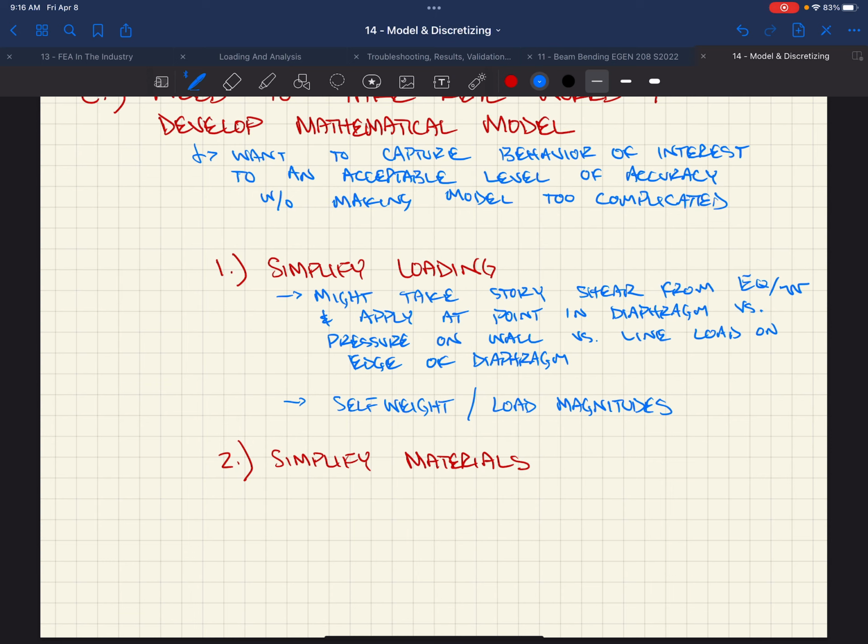And then you would go to that manufacturer and they would say, okay, here's a table: if you have a double wythe wall on the outside, you're gonna need to use this clip at this spacing, right? Maybe 48 inches on center horizontally, 48 inches vertically. And then they do a bunch of testing, because you can get away from analysis if you're able to put it in the lab and verify that it can handle it, right? There are some factors of safety associated with it.